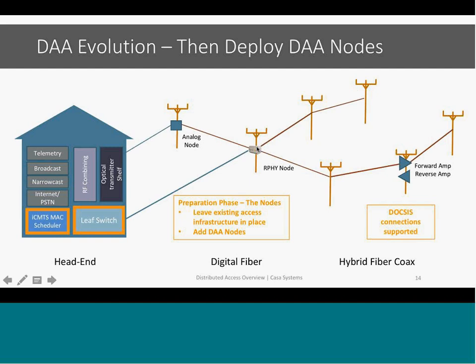The importance, with the spec called out, was now my ability to tap into that existing coax, so I can service all these users off this remote PHY node and get out to my end subscribers. Per the spec, if it's DOCSIS compliant, that stays. If I have cascades and EDFAs and amplifiers, all that will stay. But I'd be able to eliminate some equipment because I've pushed it from here out to here. Now I have 1.2 gigahertz of spectrum available with a launch power that might not need amplification out to some of these endpoints.